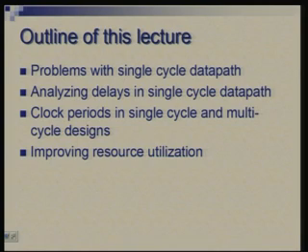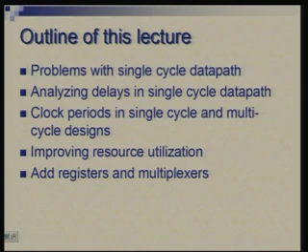The resources are the main hardware components we have in our data path, and what we will do is try to share these components such as memories and ALU. To facilitate that we would need to introduce some more components, but of a lower cost generally. These are registers and multiplexers.